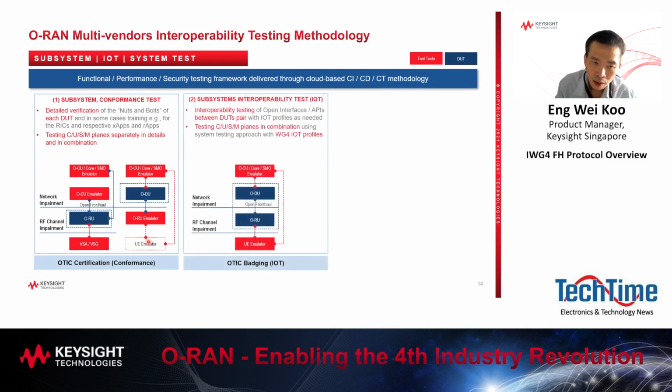On interoperability testing, this is when you test your ORU and ODU in isolation. They pass all the tests for conformance and subsystem testing. You start to look at testing them in pairs, right? So you have the UE emulator emulating a lot of UEs, and then connecting to the ORU over the RF interface, either using a conducted mode cable connection or over the air. And then after that, the ODU as well is the device under test, with the backend connected to an OCU, a core network, and an SMO emulator.